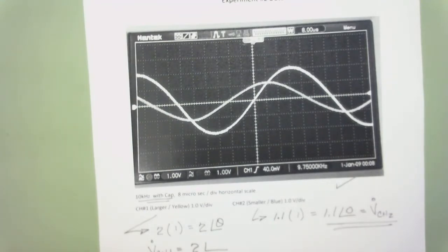So I could say then that my frequency, of course, is equal to 1 over the period. So I'm going to say that this is 1 divided by 2 times 51.2 times 10 to the minus 6. Now we need to go back and use the base units here, because we don't want to use the microsecond. Where'd the 2 come from? Well, of course, that is because this was only for 180 degrees. It wasn't for the whole 360, so I had to multiply that by 2. So we'll go through the math there.